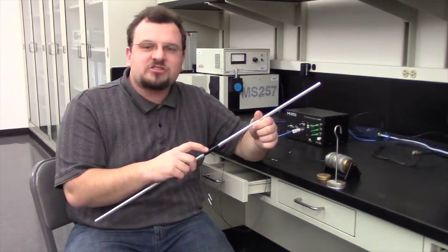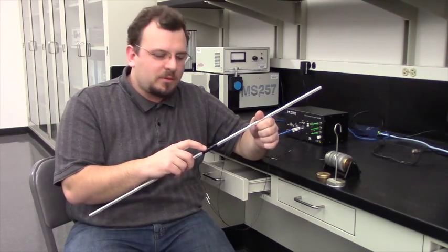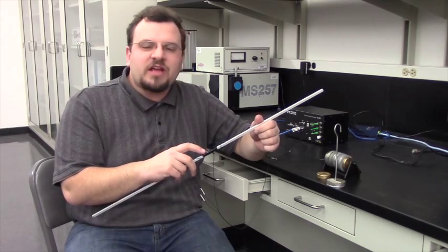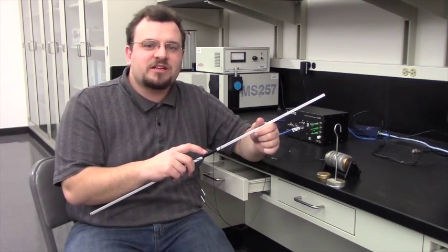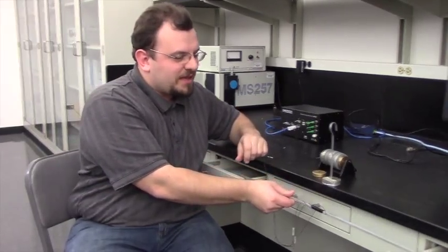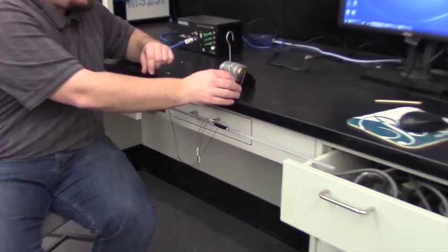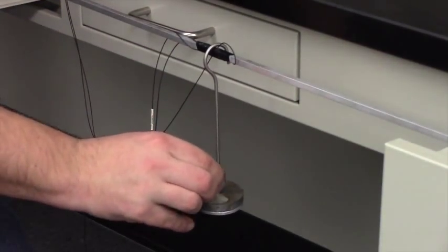Here, we have mounted a strain gauge to the bottom of a beam to measure how much the beam stretches when placed under load. At the same location, we have also placed a temperature probe to separate any temperature components to mechanical components of the strain. The beam is then placed across 2 points and put under loads in 100-gram increments.